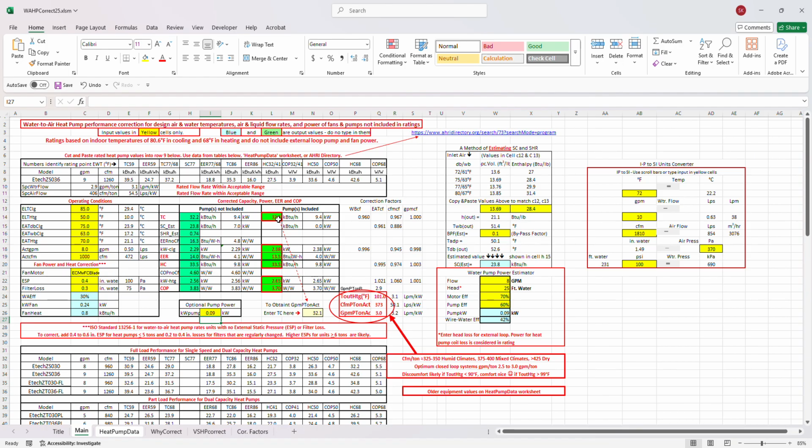So it does that when we add all these, the power for the pump and the fan, and make these other adjustments. Now, on the heating capacity, you can see the heating capacity that results is pretty much the same as the rating, okay? It didn't affect it much, because the fan heat helps keep that capacity up.